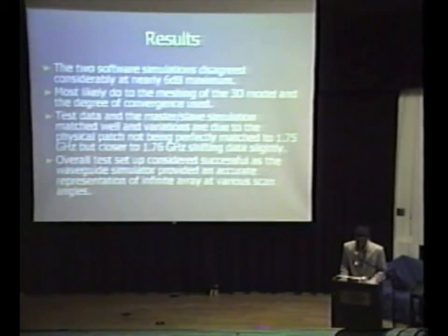The test data and the master slave simulations matched well, and variations are due most likely to the physical patch not being perfectly matched to 1.75 gigahertz, but closer to 1.76, shifting the data slightly. Overall, the test setup was considered successful as the waveguide simulator provided an accurate representation of infinite array at various scan angles.